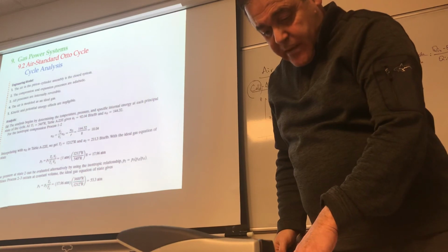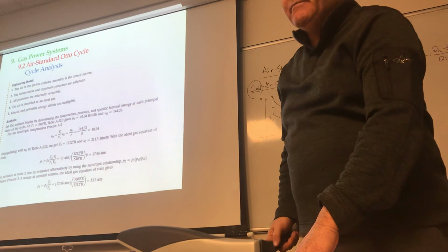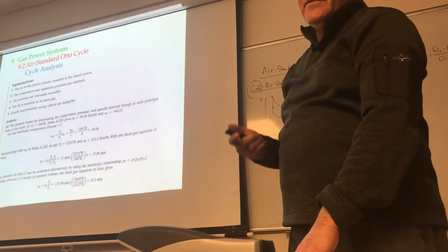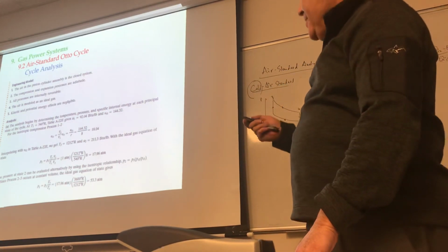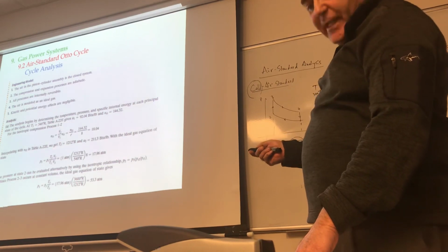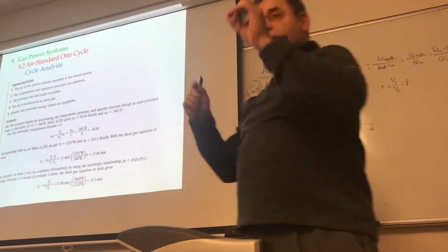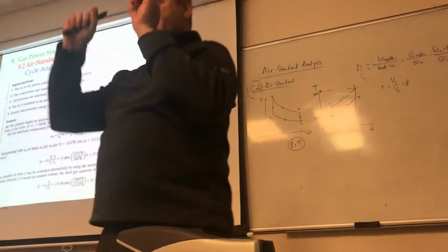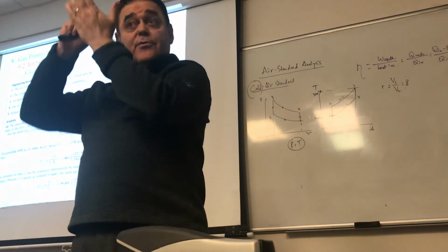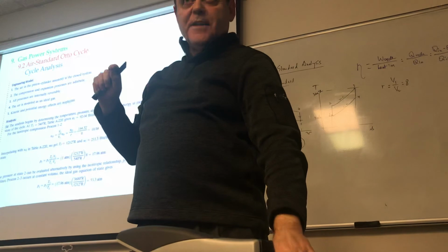Well, it's between 1200 and 1240. To find the exact value, you have to do interpolation, okay? So if you do the interpolation, you will get 1212. You see, for isentropic processes, it's the VR values that you use to figure out what the end state is. See, we did not move from this table, everything is there.